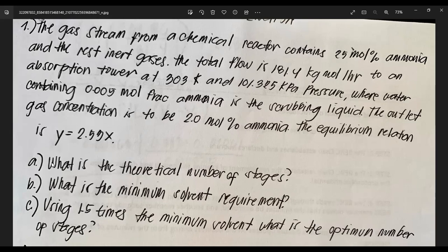But in the case of Nika, who used the table in A.3-22, you'll be able to see, though it's not the exact mole fraction, but I think it's acceptable that for a 0.0201 mole fraction of ammonia in the vapor, that's YA, at a temperature of 30 degrees, which is also equivalent to 303 Kelvin, you have the equivalent mole fraction of ammonia in the liquid, which is 0.0167.